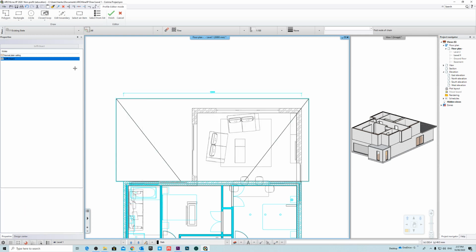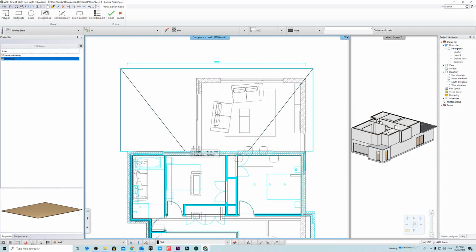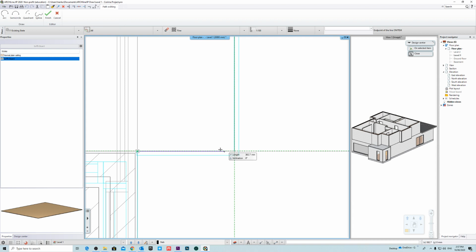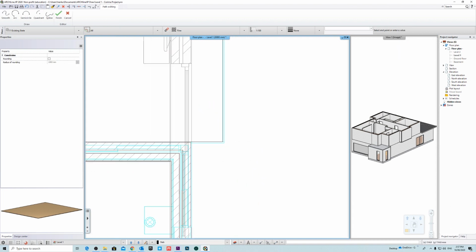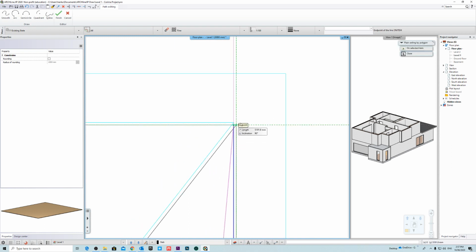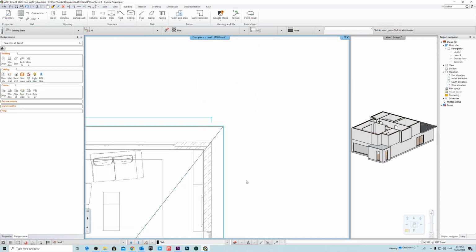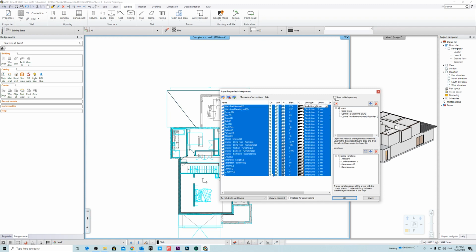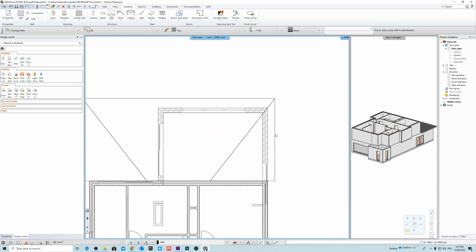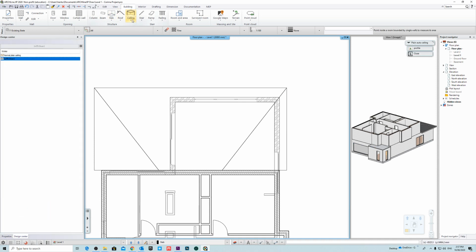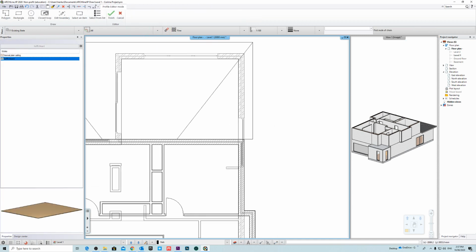Okay, so that's fine. Okay, so now all we need to do is I'm just going to trace. Okay, so the fascia board is actually going to go over the soffit board. Okay, so it needs to be on the internal side. Okay, now let me just do one thing quickly. So I'm just going to quickly hide this DWG underlay again. So just go like that, and we'll get back to what we were doing. So we'll go to ceiling, just click on plain ceiling by polygon.